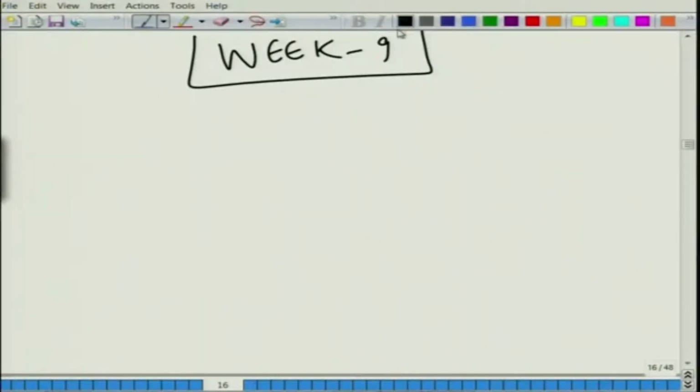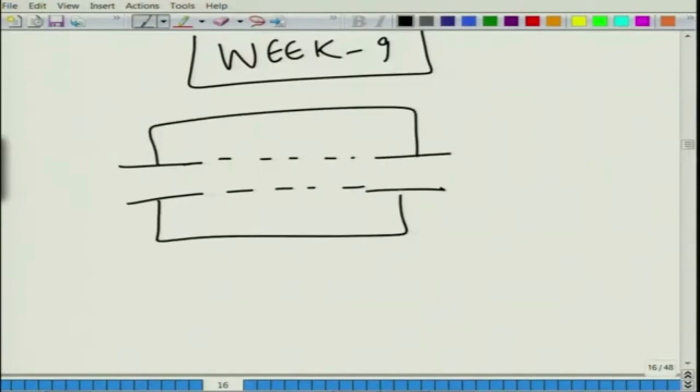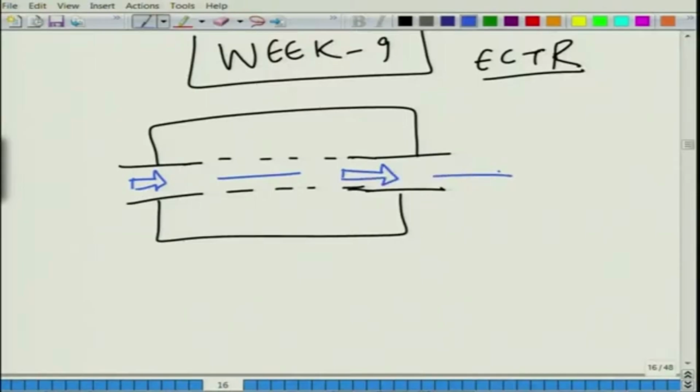let us go in a very systematic manner and try to draw this thing. So, this was an ECTR, an extended concentric tube resonator with extensions at 1 and 2, something like this. Now, suppose we have this element and then the flow really just sort of grazes the boundaries. The flow just grazes the boundary. The flow is not allowed to go through the element. Basically, the only way the flow can go is through the pipe.